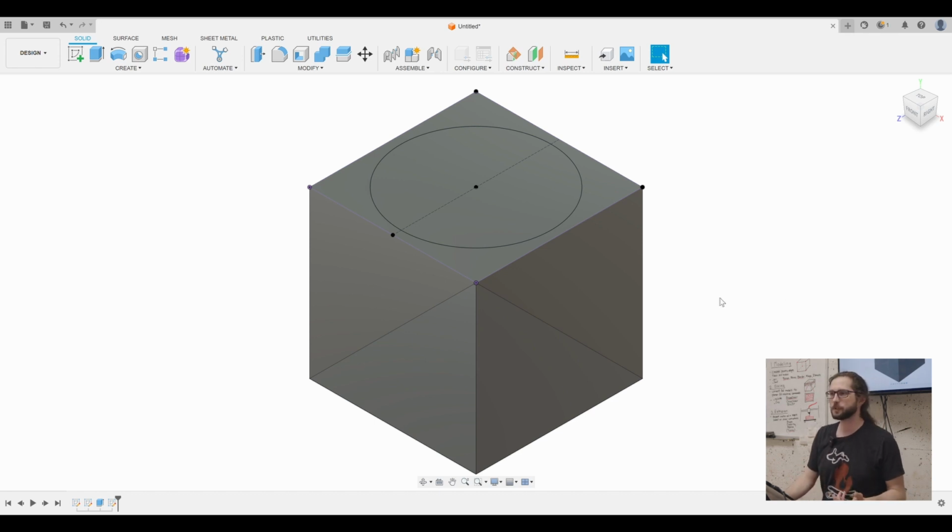So we're going to use the extrude command again. And we're going to click on the circle that we just created. Notice that Fusion will give us a couple options based on this drawing. I could actually extrude anything that's enclosed by a drawing. So I could choose to extrude the outside of this circle instead of the inside of this circle, which could be useful, right? Or it's just a different way of constructing something. For example, maybe I wanted a really thick, solid bottom, and then I wanted this cylindrical thing to extend beyond just the outside.